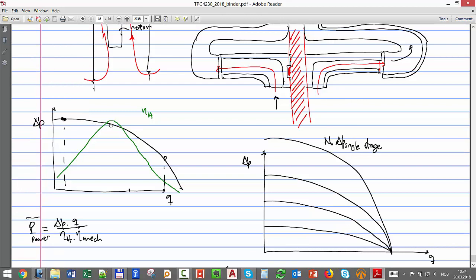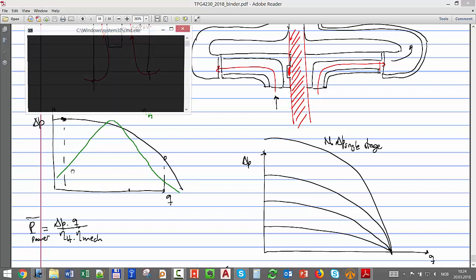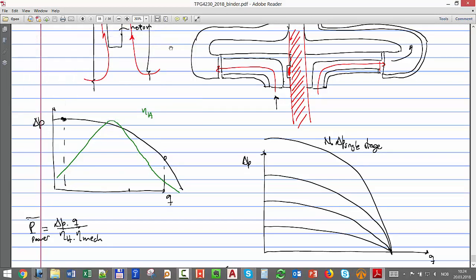And the performance, I told you, it's not exactly like an IPR, but it looks like an IPR. It has this shape. Of course, some ESP pumps also have kind of a maximum and then go down, but that's how it looks like, such that if you think about it, you have high pressure but low rate, and then you have a high rate or low head. Okay, because energy is the combination of both. So you have the same energy, you can have either one big, the other small, or the other small, the other big, or something in between.